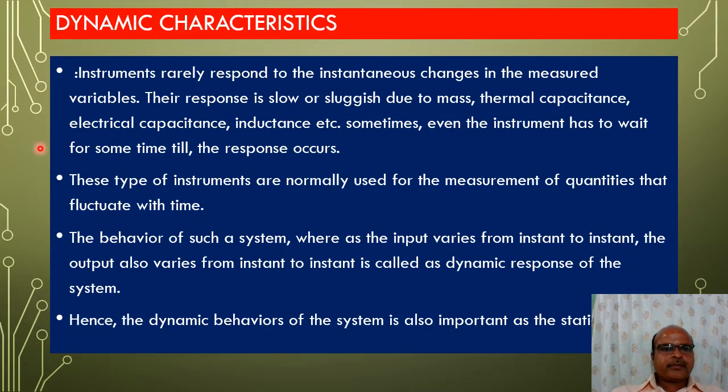Next definition, dynamic characteristics. Till now, whatever characteristics we have mentioned are static characteristics. Next we have to mention dynamic characteristics. Instruments rarely respond to instantaneous changes in the measured variables. Their response is slow or sluggish due to mass, thermal capacitance, electrical capacitance, inductance, etc. Sometimes the instrument even has to wait for some time till the response occurs.